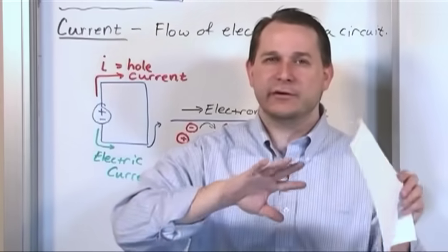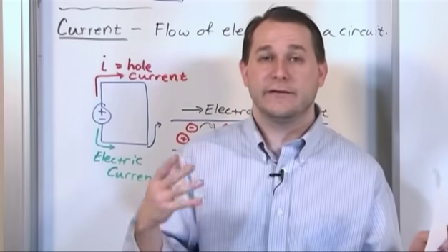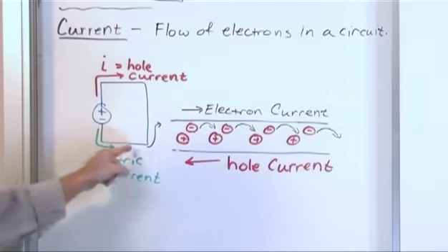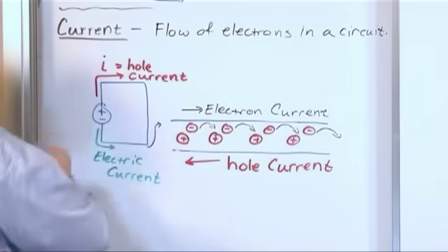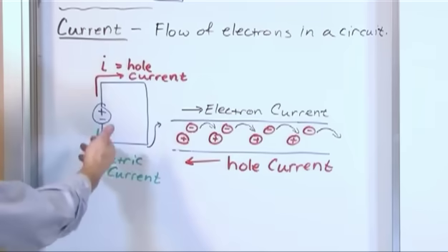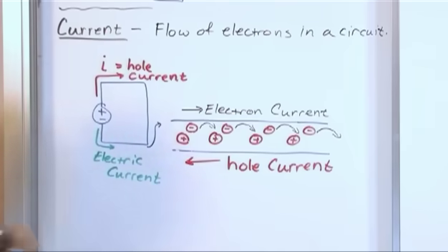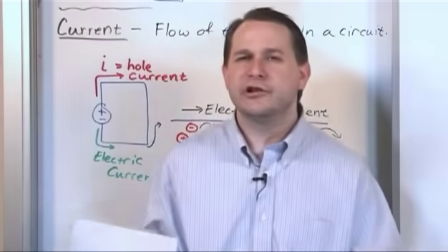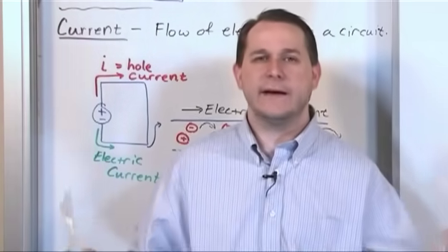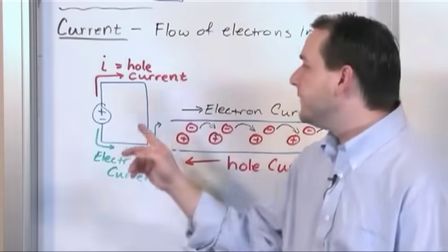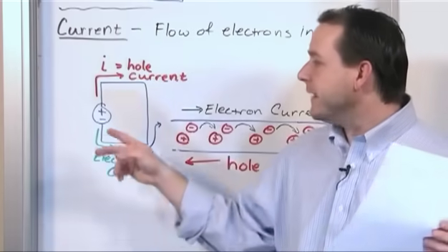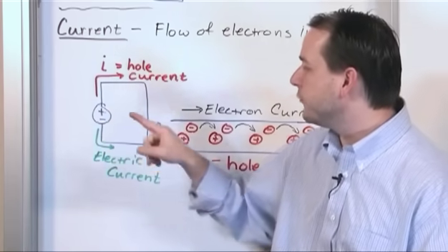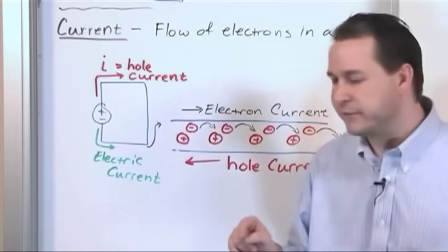But in any kind of an engineering course, when you're taking a circuits class, you never ever talk about the electron flow in this direction, you always instead talk about the positive current flow. It's the same value going in opposite directions, and it makes the equations much, much simpler. And in fact, all the power calculations, the function of the circuit, the energy, everything is completely and totally described by talking about this pretend current that's going in the opposite way. So just get used to seeing that. You're always going to pretend that your current's coming out of the positive terminal, even though in reality the electrons are bleeding out the other side.